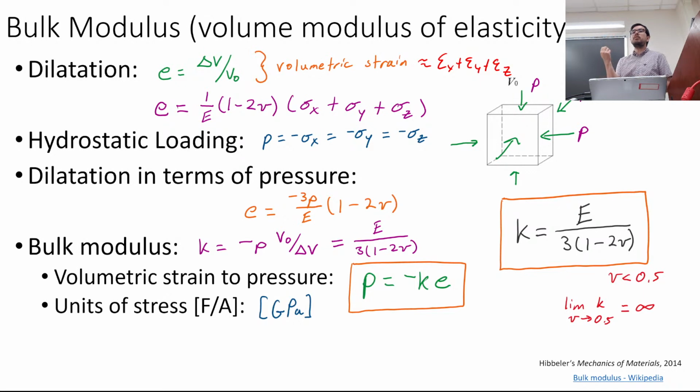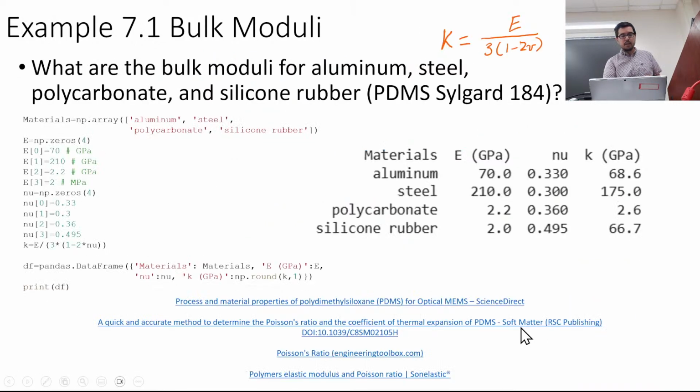But the rubbery materials actually have a Poisson ratio of approximately 0.5. For numerical simulations and various other things, we usually use something like 0.48 or 0.49 for that value. But it's just something to note that can be a problem.